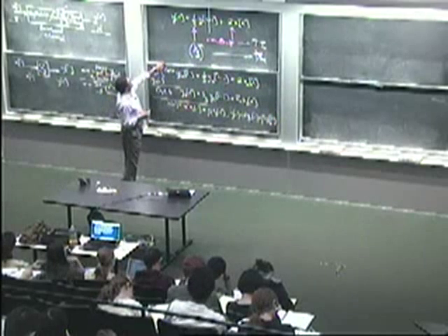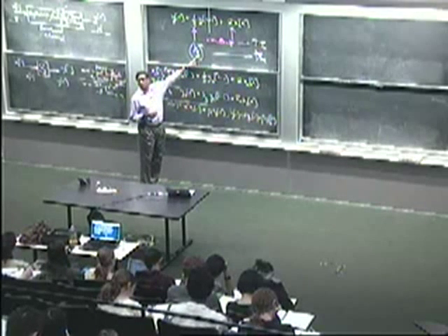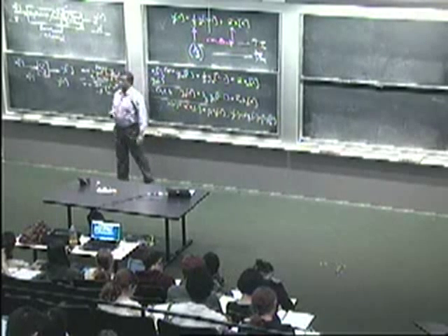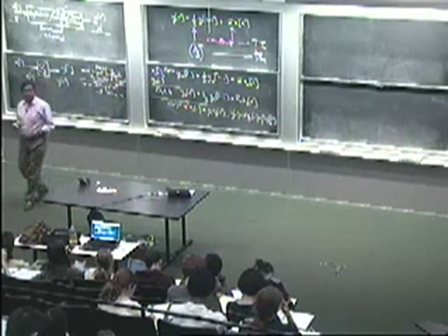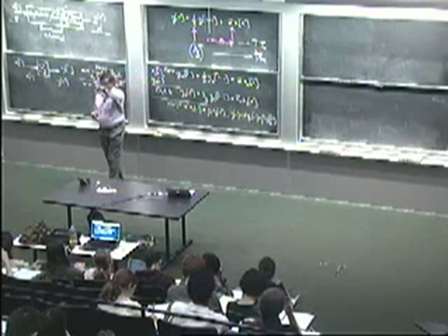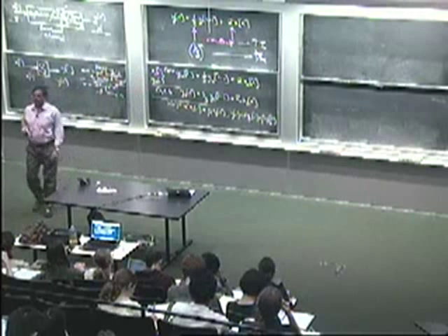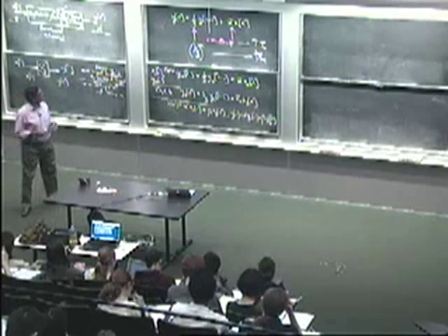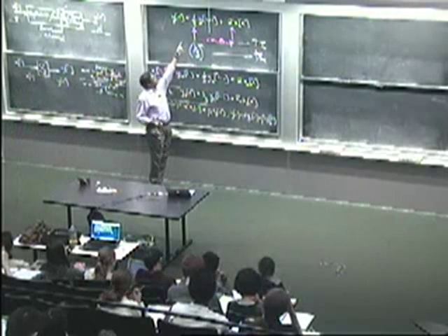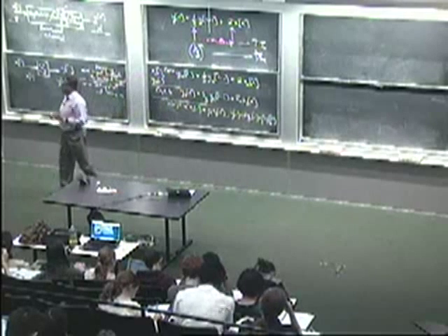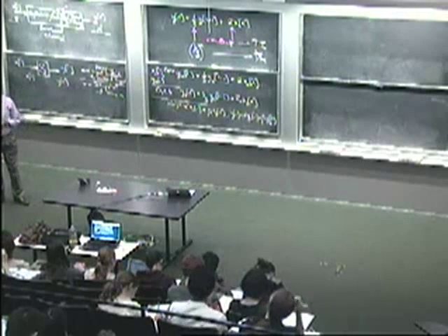What about if I had changed this to 1/3 to the power n? So I had a time-varying expression of this type. So I have a time-varying system. Do you think this system would still be linear? If you work through it, you'd see for the same reason that superposition still works. So if I had 1/3 to the n there instead of 1/3, I'd get a time-varying system, but I could still superpose solutions. It would be a linear time-varying system. Okay?